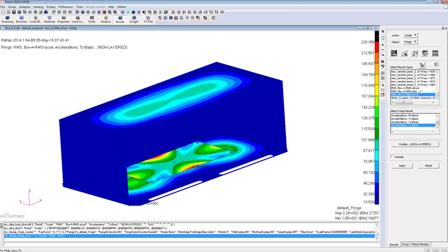So that's one of the things it gives me, a frequency response we can look at there as well. I guess the 2 cents on that is that if we want to look at stresses, displacements, things like that from the frequency response, we can do that. But when we do the assessment, who's worse, we have to look over the entire frequency range. Again, possible, but looking at the overall model, overall comparison, that's a little bit more work. Okay, so how did I get here?